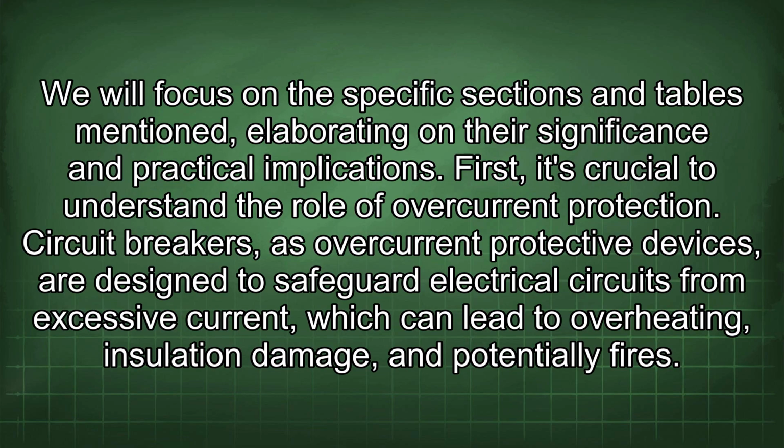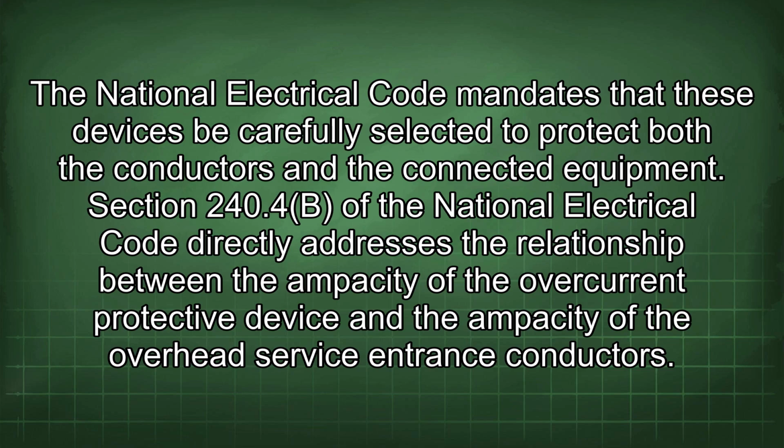First, it's crucial to understand the role of overcurrent protection. Circuit breakers, as overcurrent protective devices, are designed to safeguard electrical circuits from excessive current, which can lead to overheating, insulation damage, and potentially fires. The National Electrical Code mandates that these devices be carefully selected to protect both the conductors and the connected equipment.